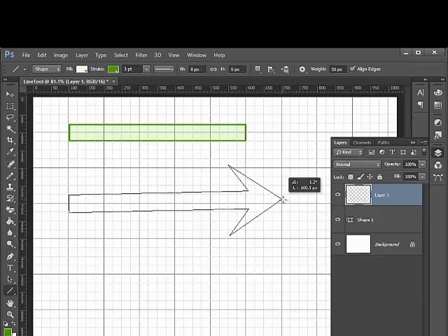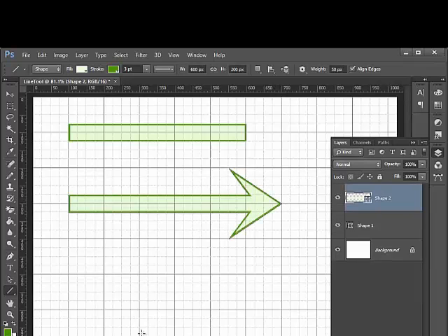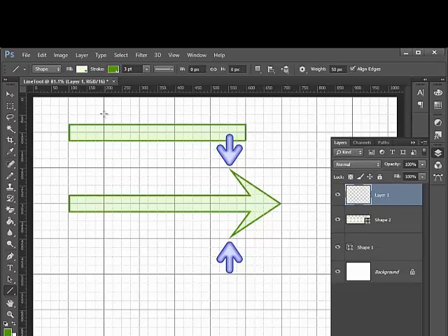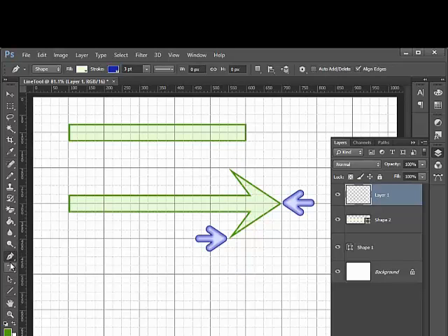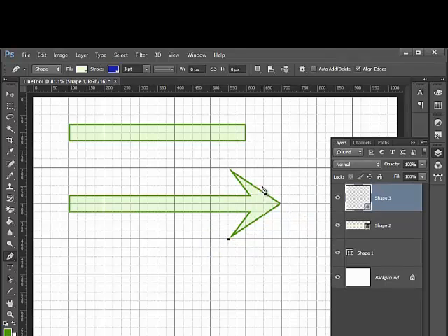Draw a horizontal line below the other one. The arrowhead's width extends over 2 major divisions in the grid, so the width is, in fact, 200 pixels. The length of one of the arrowheads extends over 1.5 major divisions, 150 pixels, as expected. To see what the concavity is measuring, we'll add a blue line that goes from one of the arrowhead tips along its edge to the center of the stem of the arrow. The 50% refers to the length of the arrowhead, which is 150 pixels, so the concavity is 75 pixels.